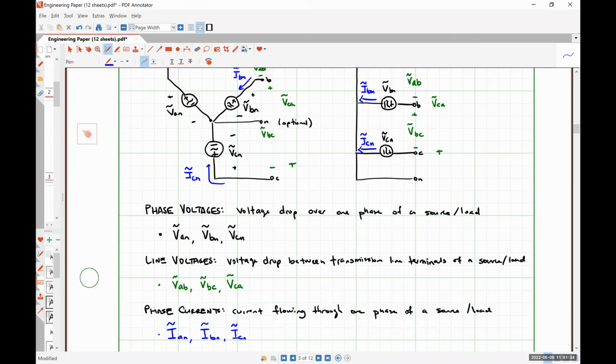And if you put an inductor in parallel with it, that's going to introduce a 90-degree phase shift as well. That's more of a poor man's way to effectively make a single phase system behave like not a single phase system, much more so than actually generating voltages that are out of phase.